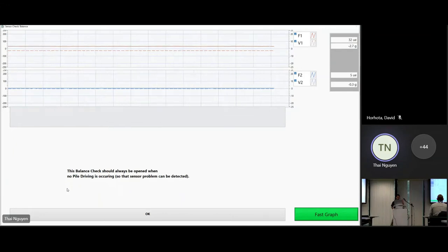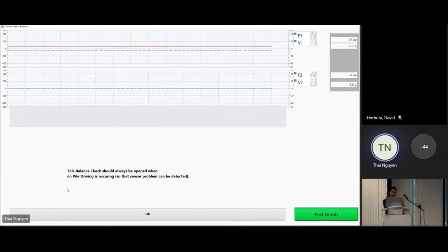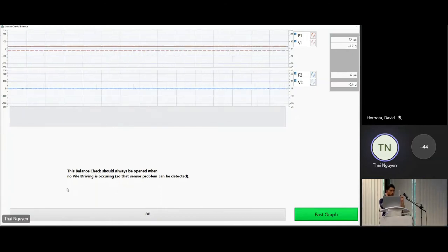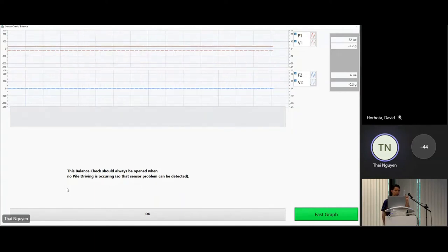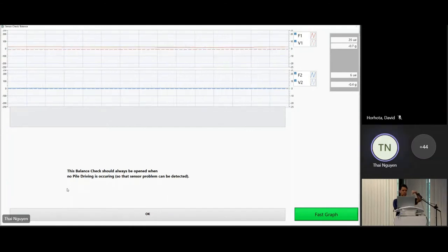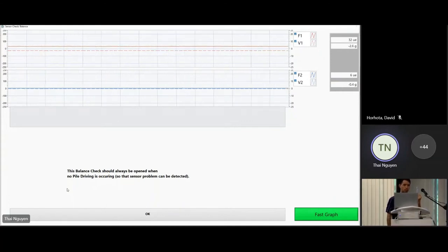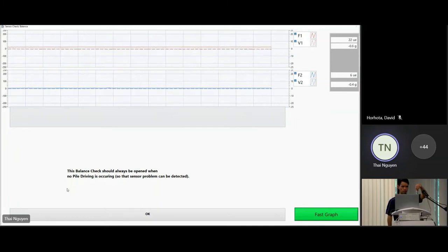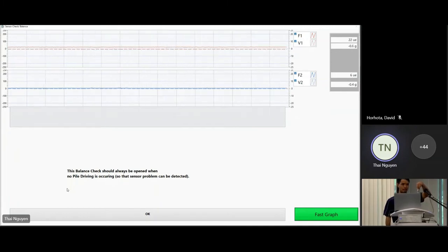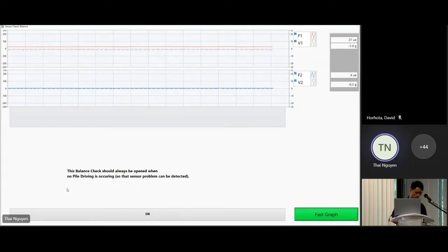When I put it like this, the static acceleration number there is minus 2.7. So that's the 0 point. If I flip it upside down, it will be different by 2. So let me flip it upside down. That's minus 0.6, and when I flip it up, it's 2.6. So that's roughly about 2G. The difference is about 2G, the static between up and down.